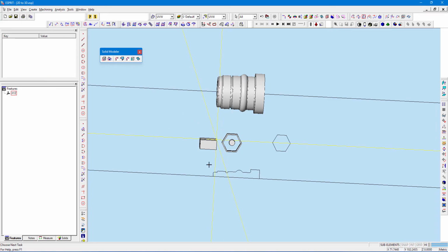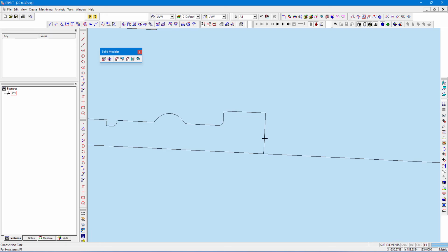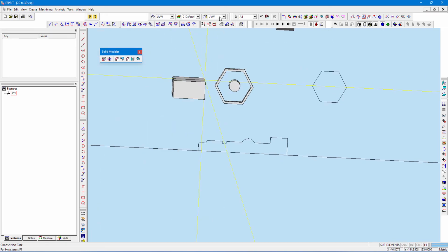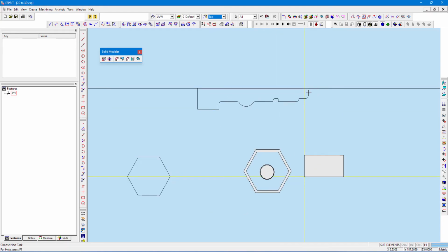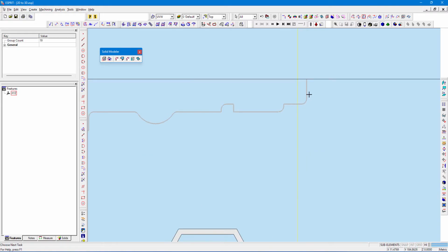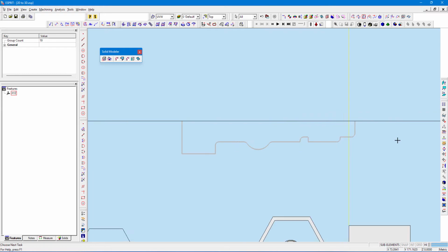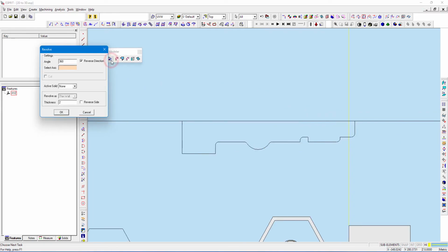For thin wall, I again go for the sketch which I just drew below, in above, and by pressing shift I will select the line, and after this I will once again select this. The total sketch profile is selected, and I will go for revolve, and again I will need only 90 degree to show you the difference here, and select the axis.